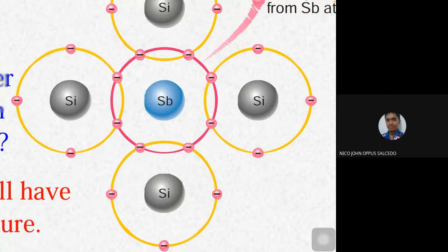Because its neighboring silicons share their valence electrons also. So that's why an intrinsic silicon behaves much like an insulator, because its bonding is stable. Even although it is only covalent, and we all know covalent is a weak type of bond, it is still stable because the electrons are paired. So that's why an intrinsic semiconductor acts more like an insulator.